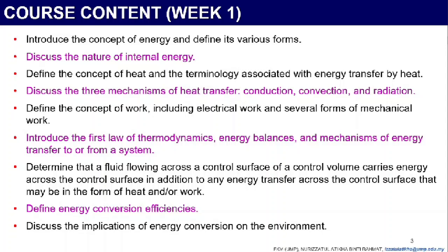I will also introduce again the first law of thermodynamics, energy balances, and mechanisms of energy transfer to or from a system. We will determine that a fluid flowing across a control surface of a control volume carries energy across the control surface in addition to any energy transfer across the control surface that may be in the form of heat and or work.